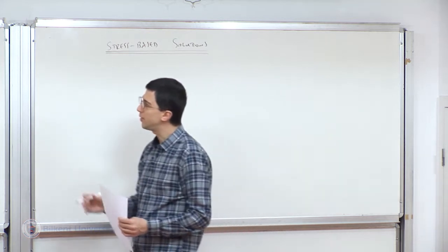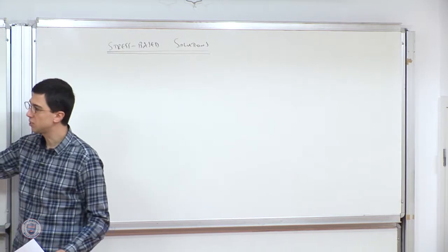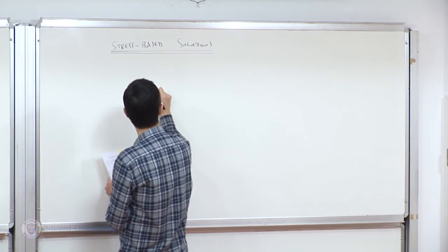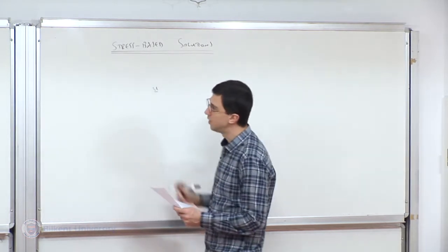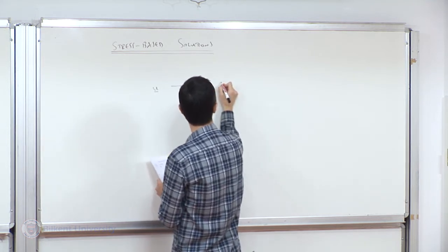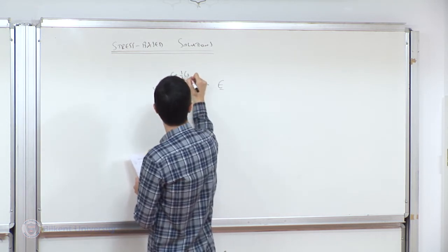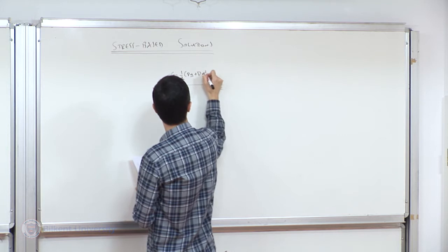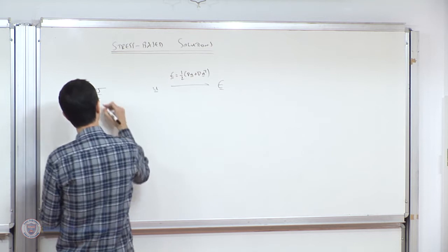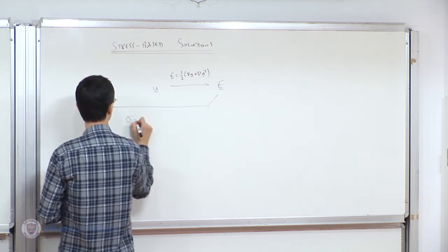So in particular, the displacement-based approach is very methodological. You make some observations, and then the procedure takes you through the solution. So for instance, remember that there we first begin with the form of the displacement, and then we calculated the strain, right? And then, of course, we have the stress, and we linked stress to strain through isotropic linear elasticity.